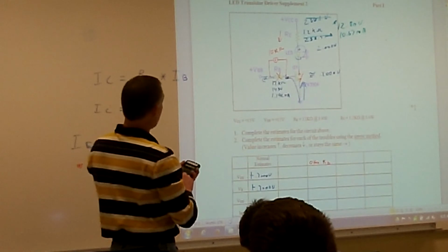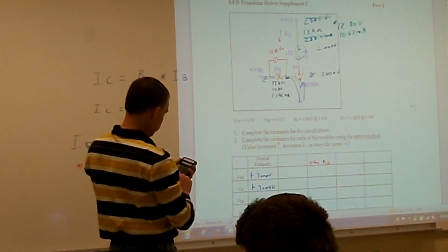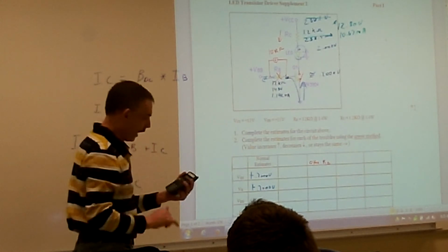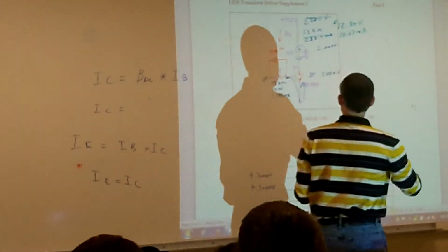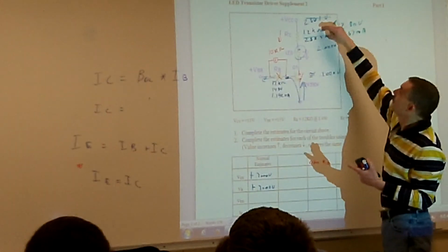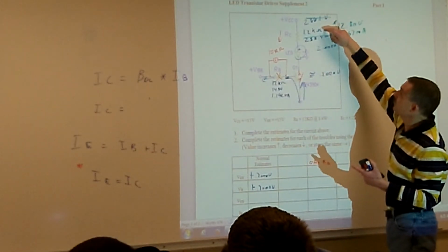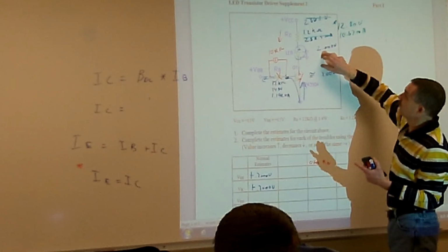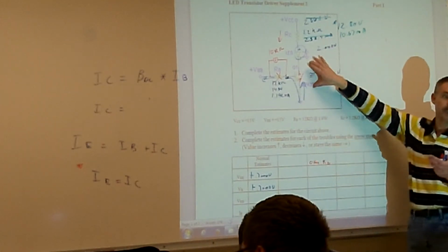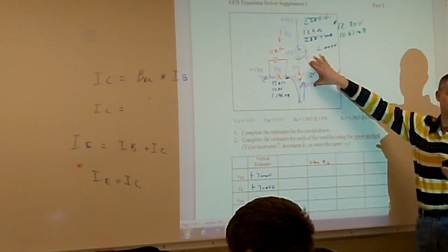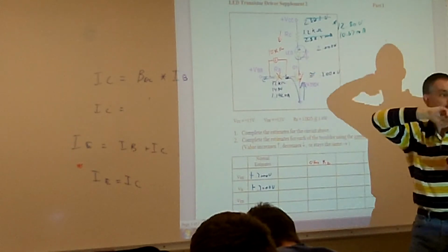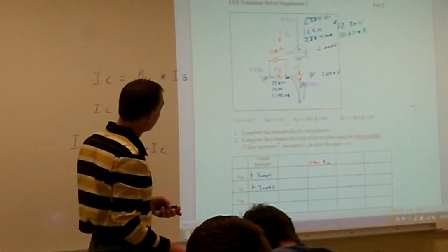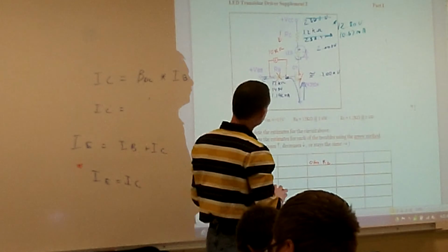And if I multiply that by my 1.2 k ohm, I'd be at about 3 volts dropped across there. I get 3 volts dropping across here, 2 volts getting dropped across my LED, and then the remainder of the voltage would be dropped across CE. So it wouldn't be in saturation, but it would be enough to get the light to dim. Yep. So that light would dim just slightly.